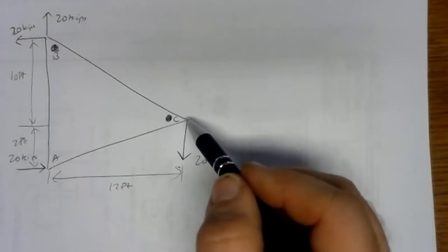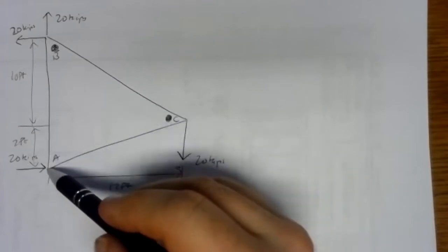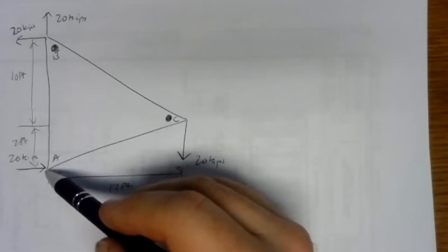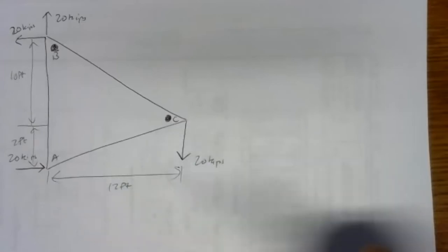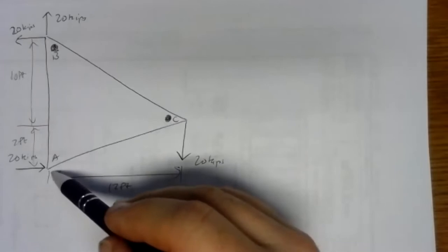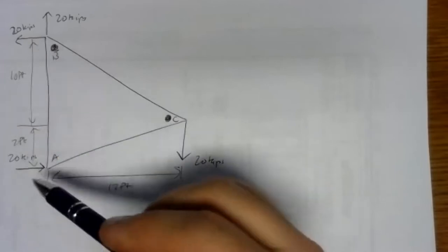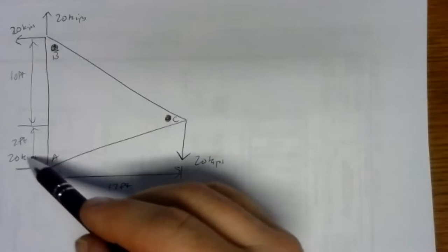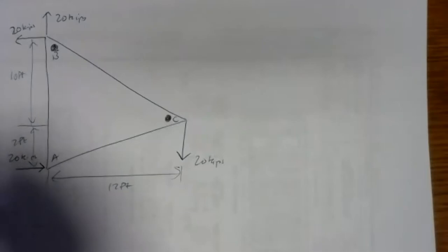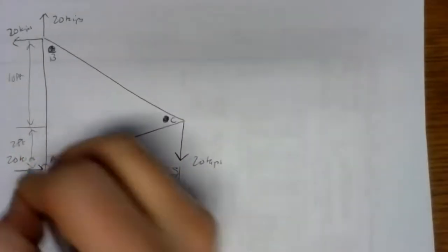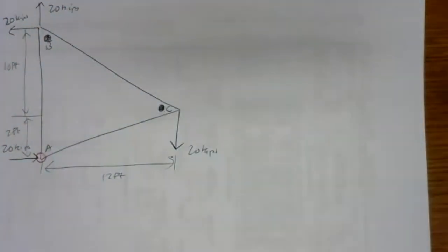And while we have the mathematical skills to do that, it's not something that I'd choose to do if I had other choices. You always want to pick joints that have at least one of the unknown members horizontal or vertical. That means at least one of the members is going to not involve sine or cosine. So joint A or joint B, either one would be easier to work than joint C. And A is slightly easier than B because it only has one external force on it. It's got that 20 kips. So I'm going to go with joint A first here, and I'll draw that one up here.